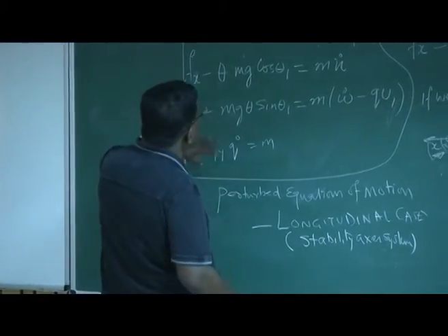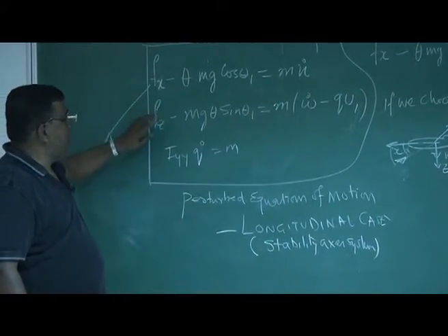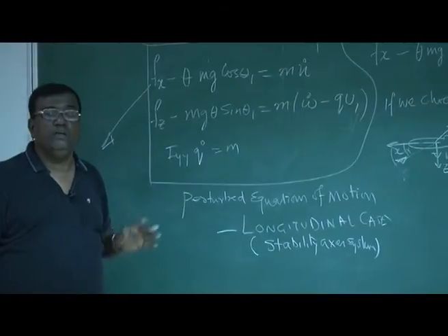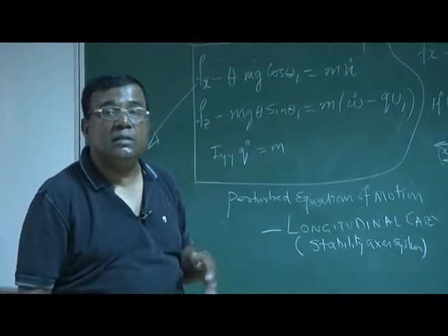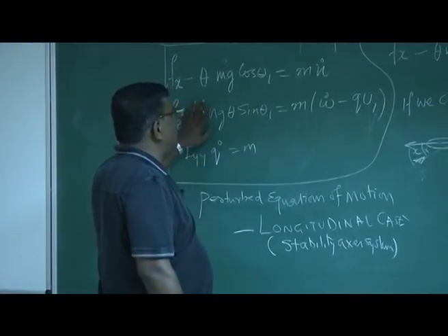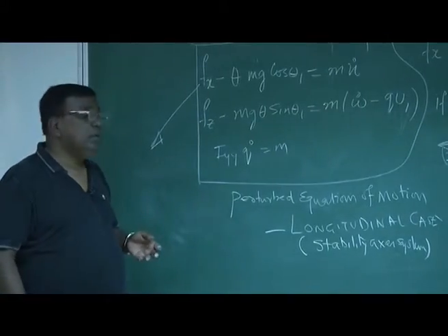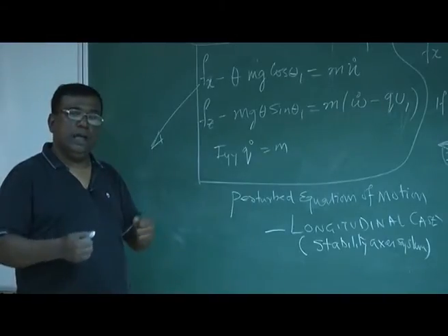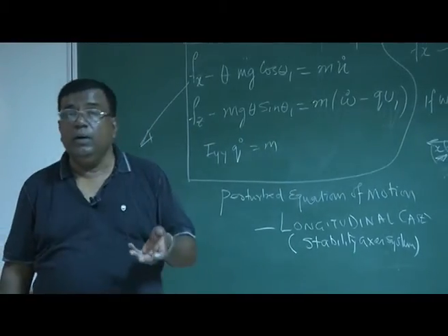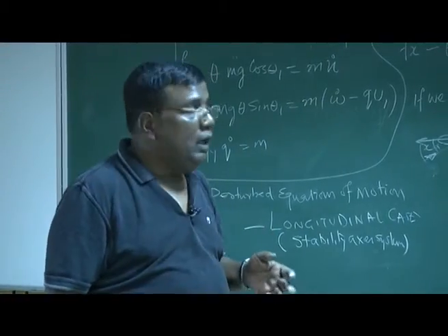So what is called for is, I need to solve this equation. I need to model Fx, Fz, and m, how to calculate Fx, Fz, and m. Once I know that, then it is simply solving a simultaneous differential equation, right? So please understand, we have come very close to developing the equations of motion where you can have our own control. Now I know whether this airplane configuration is going to be dynamically stable or not. And if you want to change the handling qualities, the natural frequency, or the damping ratio, I know how to do it.